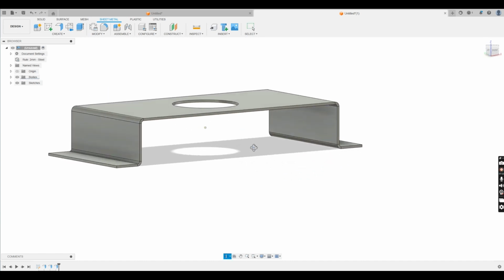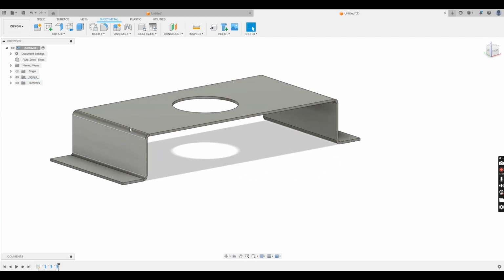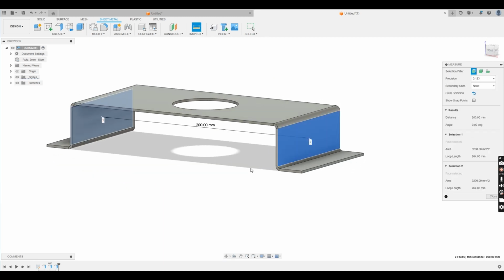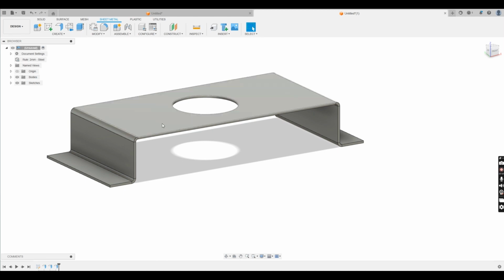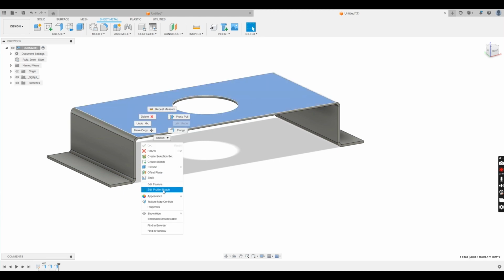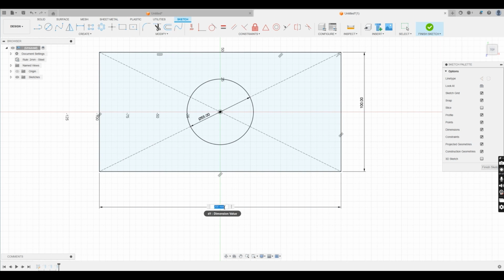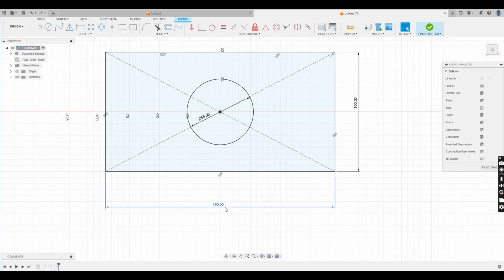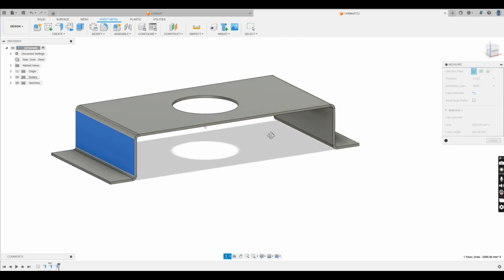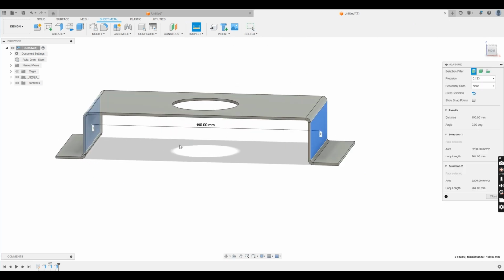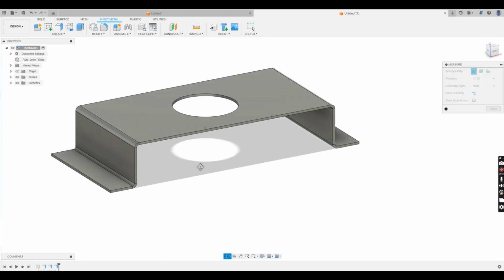Let's just say for example we've got that part made, but we want to, okay, so I'm actually going to show you here. So let's say this is critical that this face and this face are, let's say they're 200mm now, but let's say we want them to be 10mm less, so 190mm. We can do that in a way here. So we basically come in and edit the profile sketch, and in this 200 we can put in minus 10mm. You can see it's after reducing the part in width, and now if I check it again, you see I've got my 190. So that's how we can edit things like that.